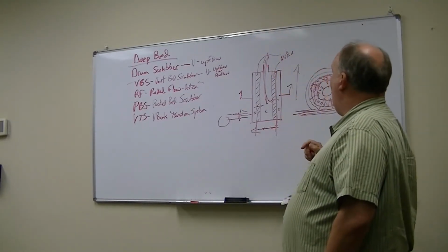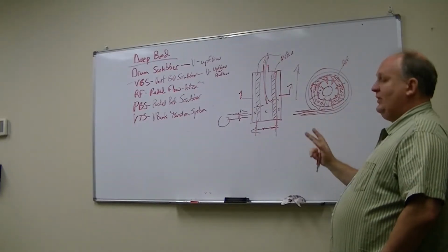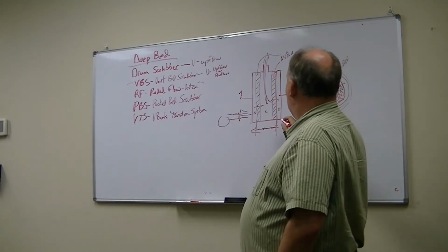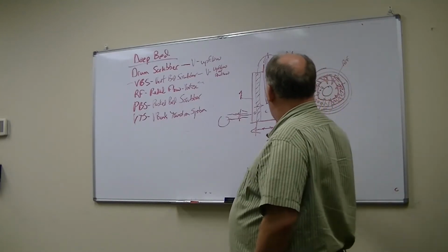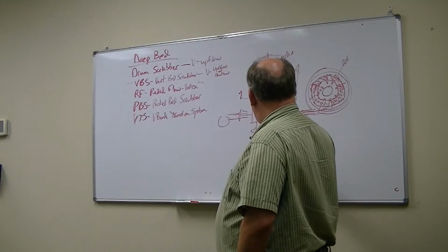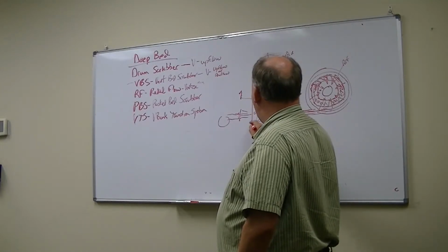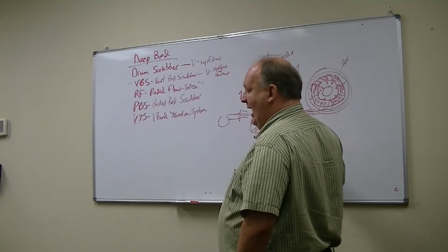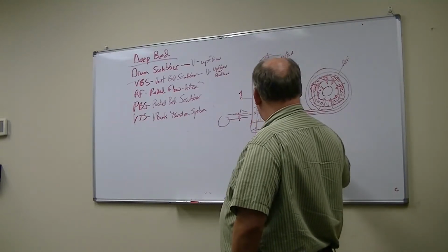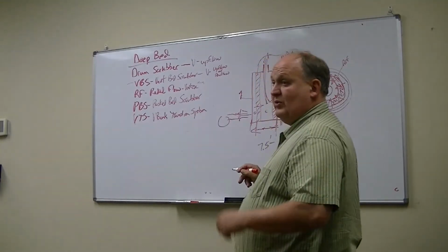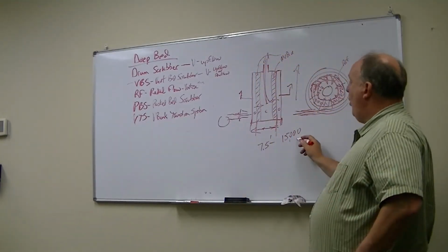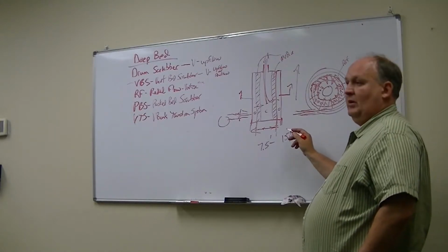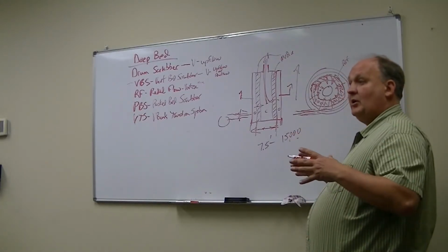Okay, so this is really nice, and typically what you can do is make a system that is 7.5 feet in diameter here, which I forget the height on it, but it can give you at least 15,000 CFM. Okay, so now all of a sudden we're able to do more airflow in a system that's a smaller diameter.